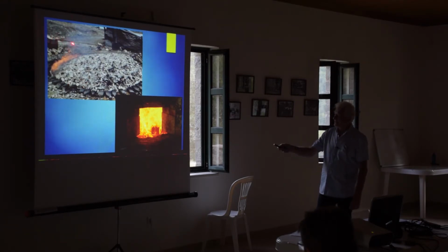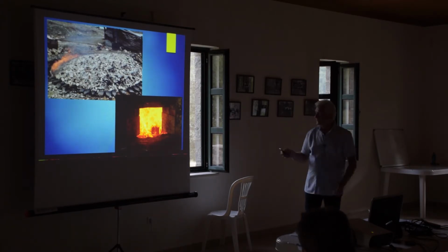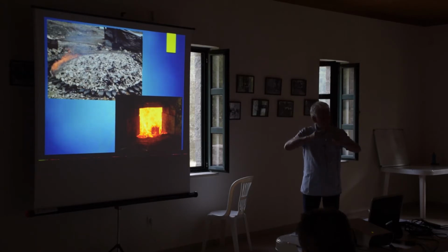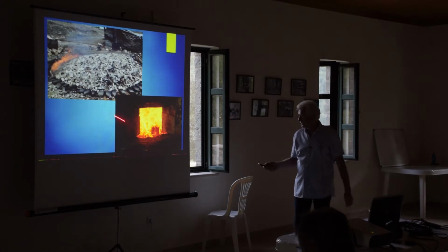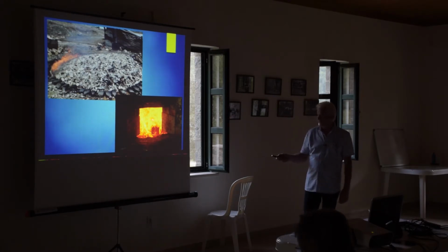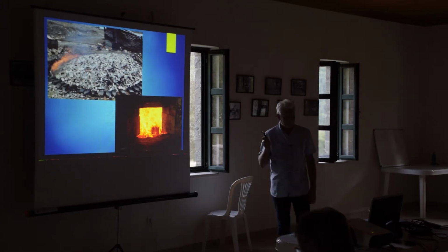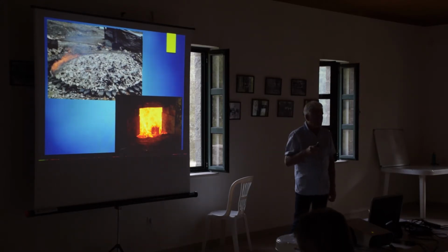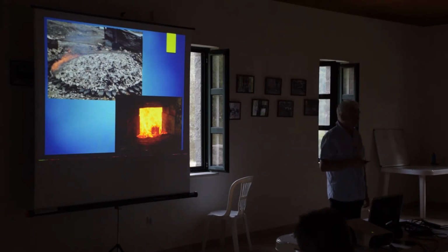You can just about see a black line here. That was the height of the stone when it was first put in. And then it drops as the burning process continues. And the whole thing is fired from underneath. In this process, for non-hydraulic lime, you have to get the fire up to 900 degrees C.